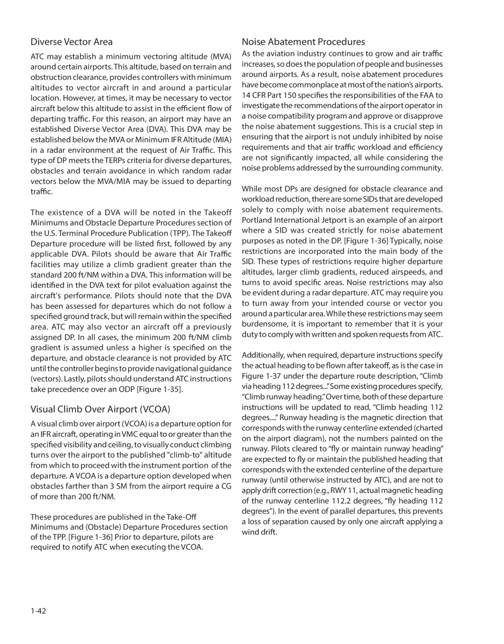Noise abatement procedures. As the aviation industry continues to grow and air traffic increases, so does the population of people and businesses around airports. As a result, noise abatement procedures have become commonplace at most of the nation's airports. 14 CFR Part 150 specifies the responsibilities of the FAA to investigate the recommendations of the airport operator in a noise compatibility program and approve or disapprove the noise abatement suggestions. This is a crucial step in ensuring that the airport is not unduly inhibited by noise requirements, and that air traffic workload and efficiency are not significantly impacted, all while considering the noise problems addressed by the surrounding community.